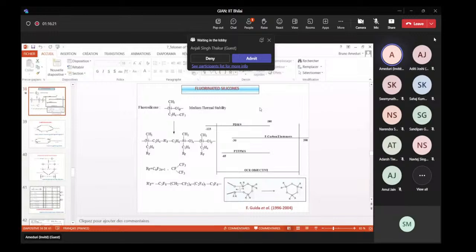So the idea is, if you consider polydimethylsiloxanes, they have a very low Tg of about -120, but the thermostability is not so high. For fluorocarbon elastomers, in contrast, the Tg is not low, but the thermostability is high. If you consider some fluorosilicones with a CF3 group, the Tg of -65 is good, but the thermostability is not so high, because these fluorosilicones undergo some backbiting, leading to cycles, and these cycles evaporate and cause poor thermostability.